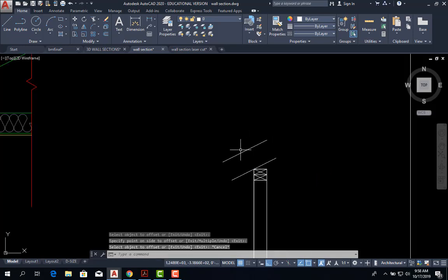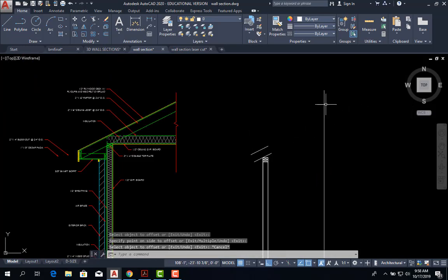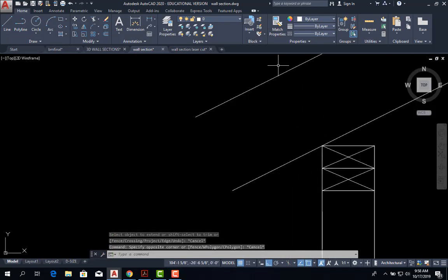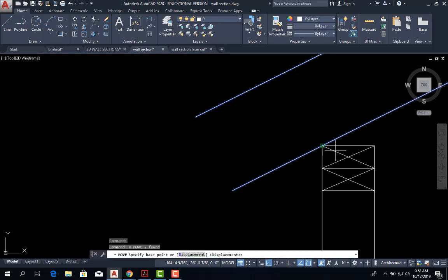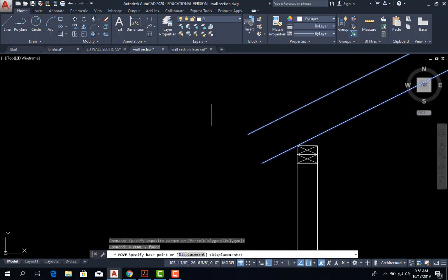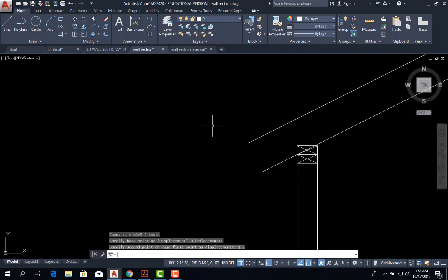So that's my rafter. I'm going to extend it, since I want to put another break line here. I'm just going to extend it all the way like that, so I know where to stop. Now here we're going to cut this, and I'm going to bring it down 1.5 inches, because here it would be hard for them to nail. So I'm going to cut this down 1.5.